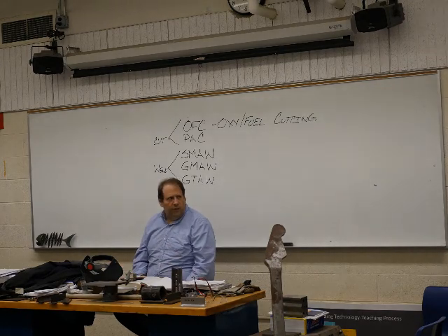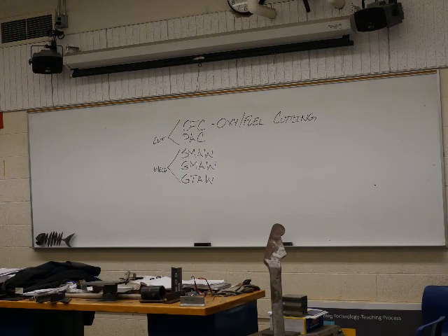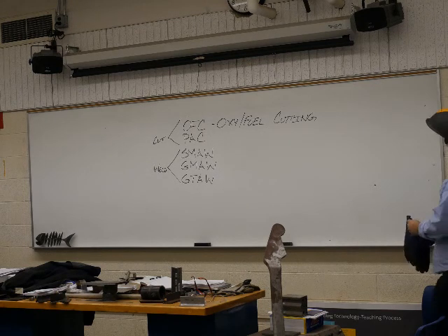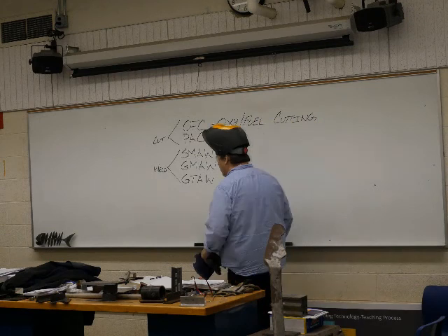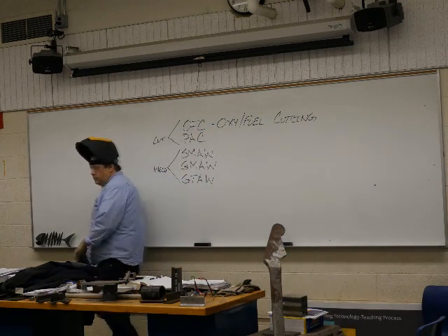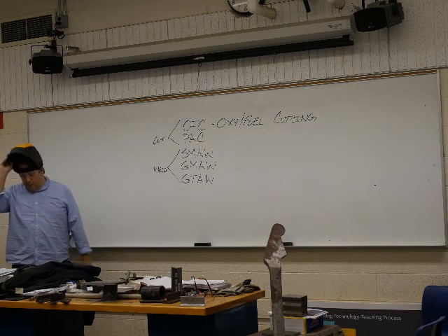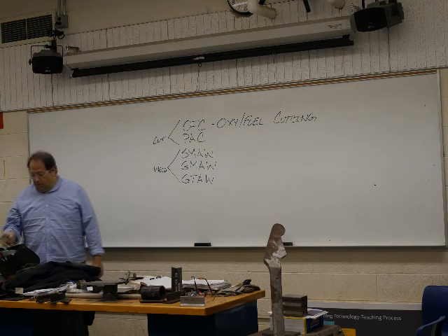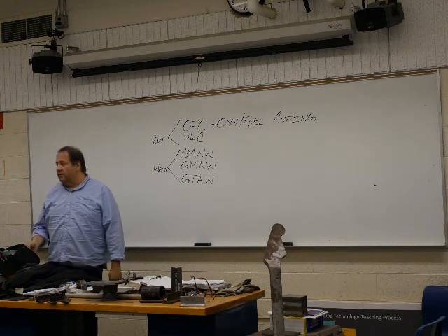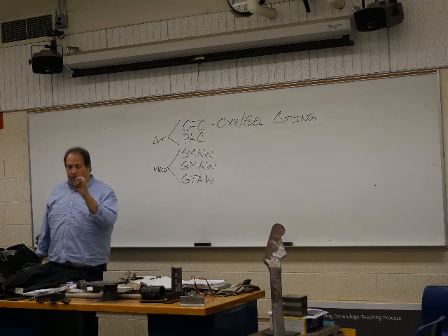So, did you have a question? So the way it cuts though, here's the thing. You got a torch, and the torch has adjustments for the gas and the oxygen, but it also has a lever. And the lever is for a high pressure string of oxygen that comes out the center of the torch tip.